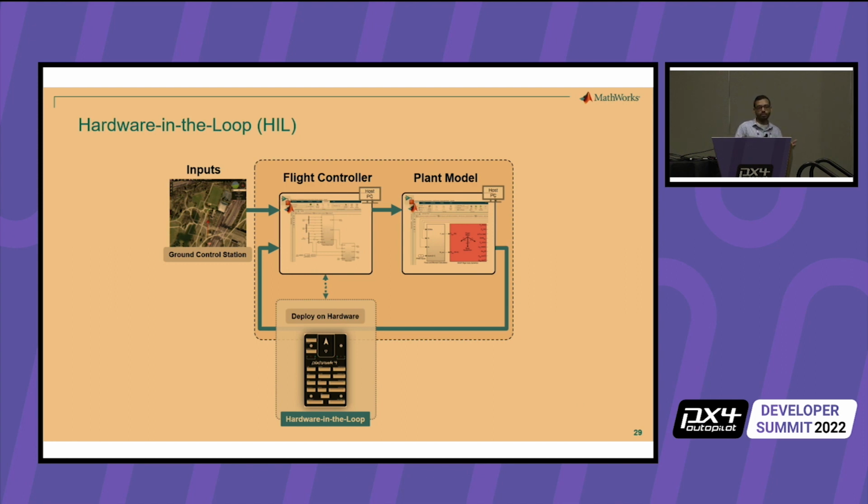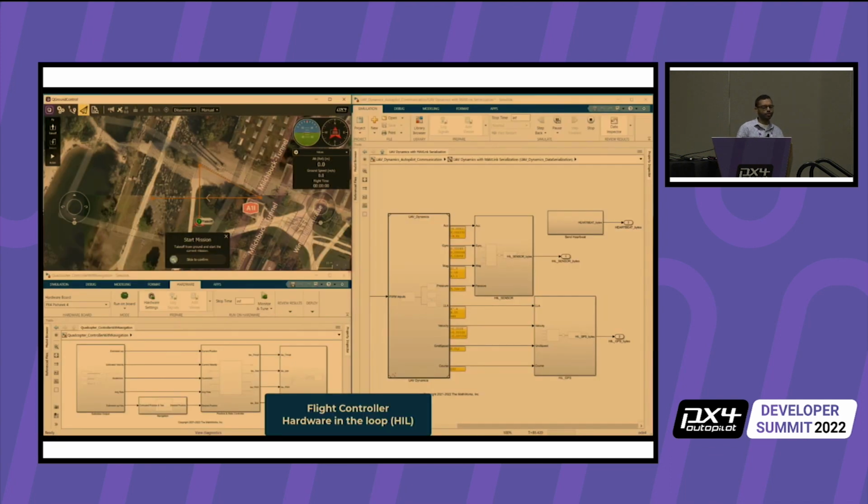So we work with the PX4 firmware. Any board that has the PX4 FMU, we can go ahead and deploy to it. As I mentioned, we actually disable two of the controllers or modules and put our own app into it. So here you can see this is actually running in hardware in the loop. I have QGC now connected, so I'm taking commands from QGC, which is going to give me a waypoint mission that I deploy onto my drone, and then I can run the mission.